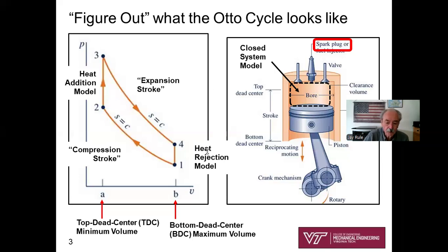All right, so let's start with the compression stroke. So imagine the piston all the way at bottom dead center. That's where the volume of the air is at a maximum. Compression stroke. I hope everybody's heard of that. There's a compression stroke where the piston compresses the air in the cylinder up to a higher pressure and temperature. At that point, the fuel, maybe due to fuel injection, is injected in and a spark plug goes off.